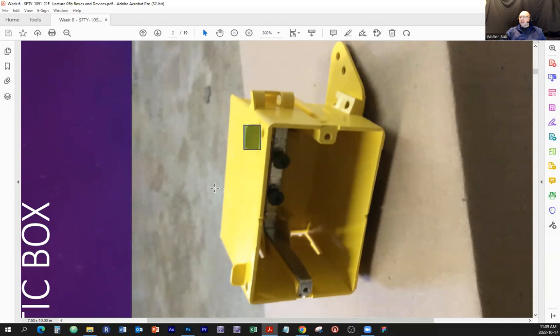Why do we put that against the timber? So there's a 1/2 inch here sticking out. What's that? It's to provide for the drywall. So normally on the timber, it would stick out 1/2 inch. But when you put the drywall on, it is going to make it flush with the surface of the box. So that's why we have those wings here.